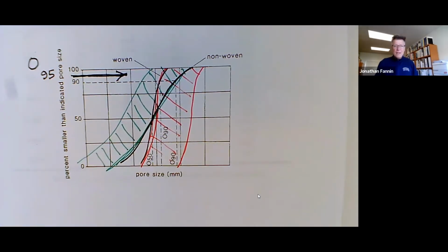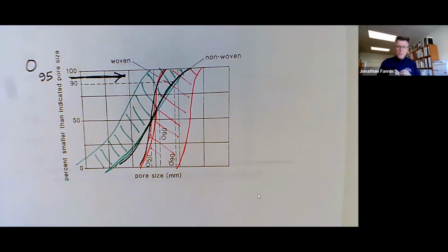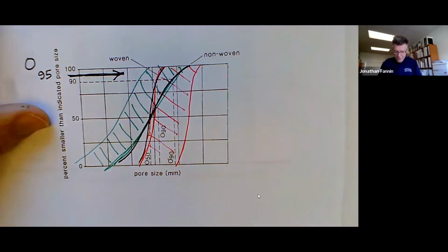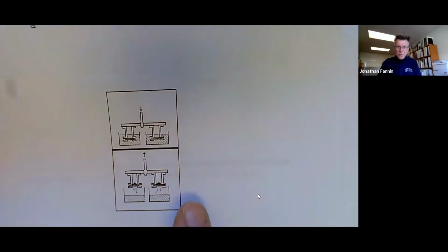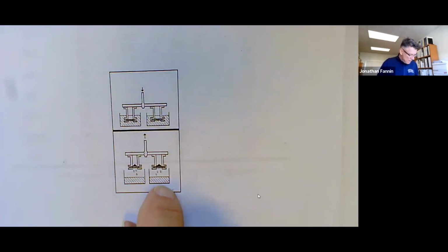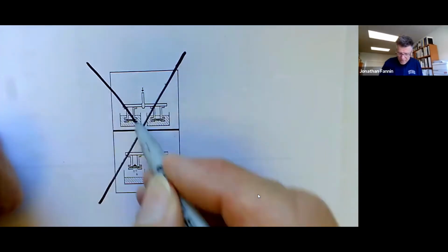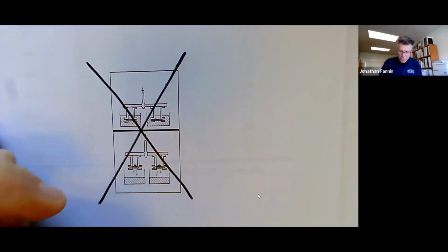That is obtained by the manufacturers either by dry sieving or by wet sieving, or even hydrodynamic wet sieving, where instead of just trying to seep particles through the geotextile, you can dynamically raise and lower it in water. I would have spoken about that, but I'm going to strike this out because that FOS test is no longer holding true.